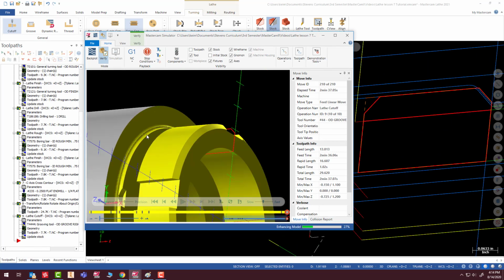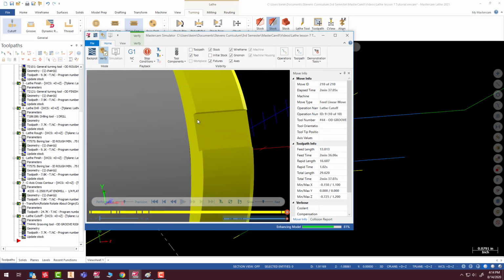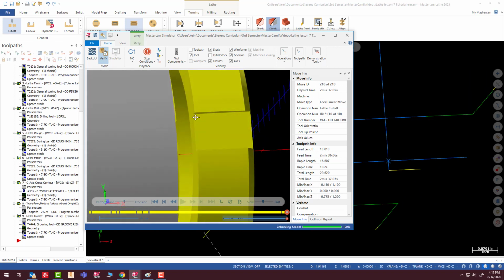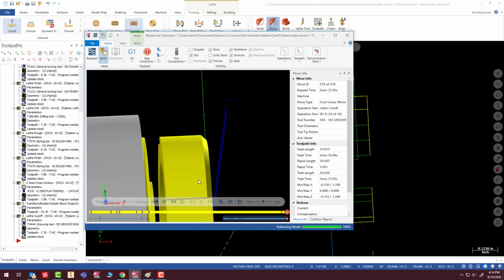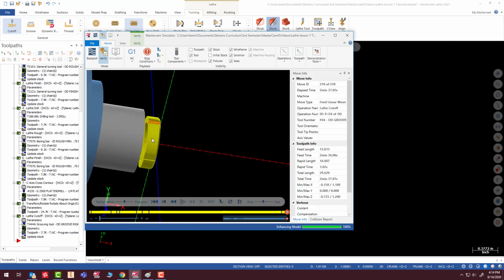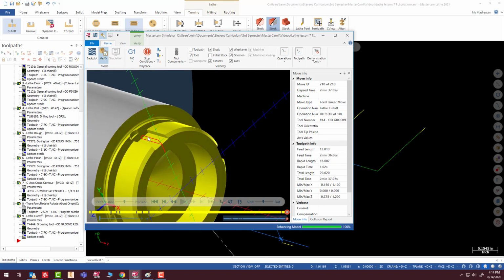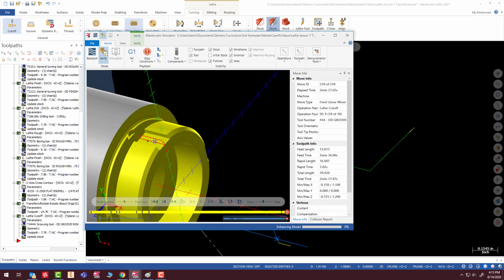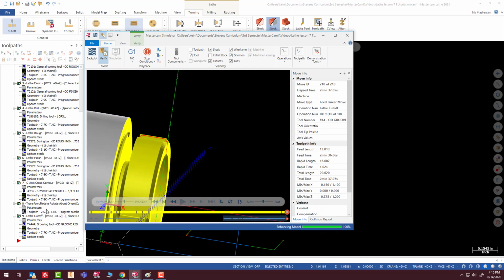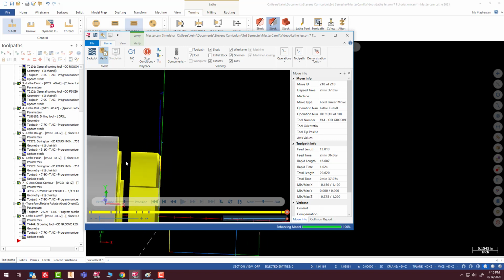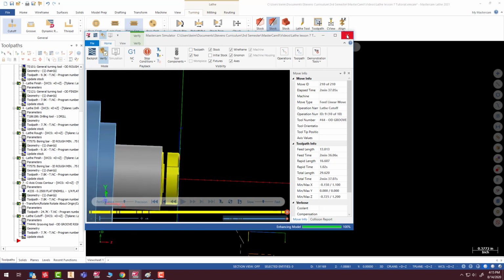so now you see the part, well, it looks good, but it's missing our chamfer. And that is going to be a bit of a problem. Now, there's a couple of downsides, things you have to think about. So, like I said, there's two ways to do this, and it depends on how rigid and how stubby your cutoff tool is. Because this will be an interrupted cut because of these notches in it, it may be a problem, but we're going to use the cutoff tool. I'm going to show you another way so we can use the cutoff tool to put that chamfer on there.